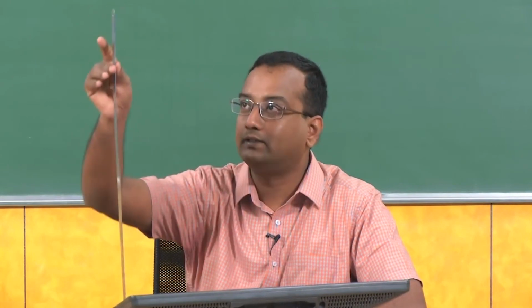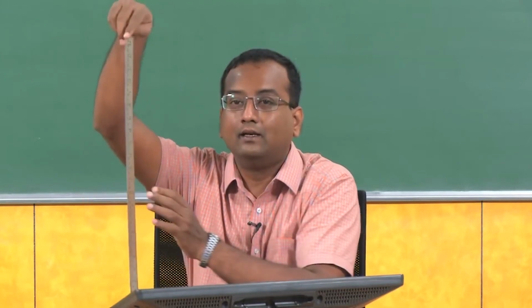I have the scale which is slender in these dimensions. I am applying a compressive force. You can see that it deforms quite significantly in the lateral direction. It is not getting compressed, it is not going down like this. If I apply a compressive force here, you can see that it is bending in either direction, but it doesn't bend in this way. It bends only in this direction or in this direction, depending upon some criteria. It bends like this or it bends like this. It doesn't do what we saw as it would do if it were a stout or a short column.